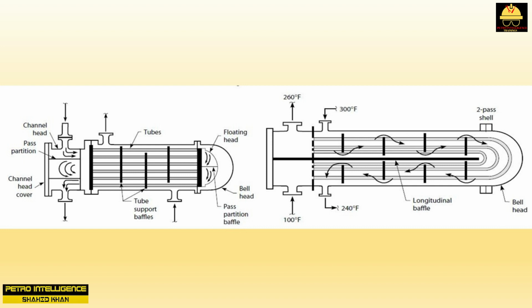Effective cleaning of U-tube exchanger bundles. Hydroblasting U-tube bundles may or may not completely clean the tubes. However, there is a method that is certain to completely clean even a badly plugged and fouled tube: pigging. Tiny pigs, that is, small brushes, are individually forced, one pig at a time, through each tube with a high-pressure water gun. One of my clients has cut open U-bends to prove the effectiveness of this pigging.